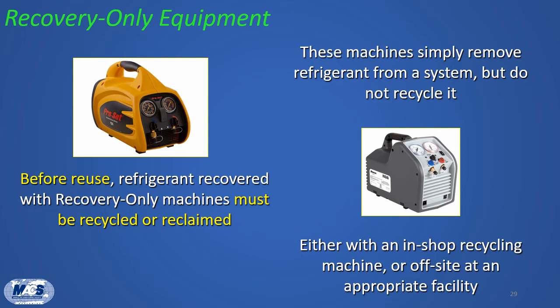Now, before you reuse any of that refrigerant that you've recovered with a recovery-only machine, that refrigerant must be recycled or fully reclaimed. These machines simply remove the refrigerant from a system and they do not recycle it or clean it. So then you would either take the refrigerant back to your shop and run it through your full-size recycling machine, or there's a lot of companies that provide refrigerant tank swapping services where they will come in and pick up your recovered refrigerant and swap the tanks out for pre-recycled refrigerant.